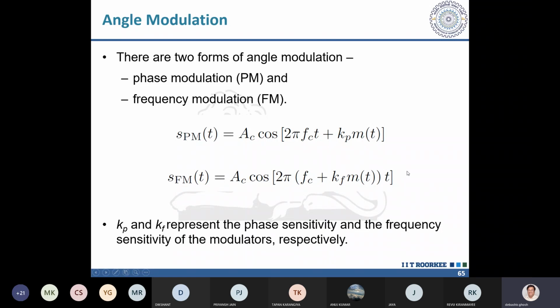Similarly, using a phase detector also, you can find out what is the fluctuation in the frequency, because phase, you know, phase difference, whatever is the phase difference, if you do d/dt of that, differentiation of the phase is your frequency. So d/dt of phase difference is the frequency difference. So basically, using a phase detector, you can do both phase modulation and frequency modulation. Okay, because frequency and phase again are related to each other. Phase is integration of frequency, frequency is differentiation of phase. Okay.